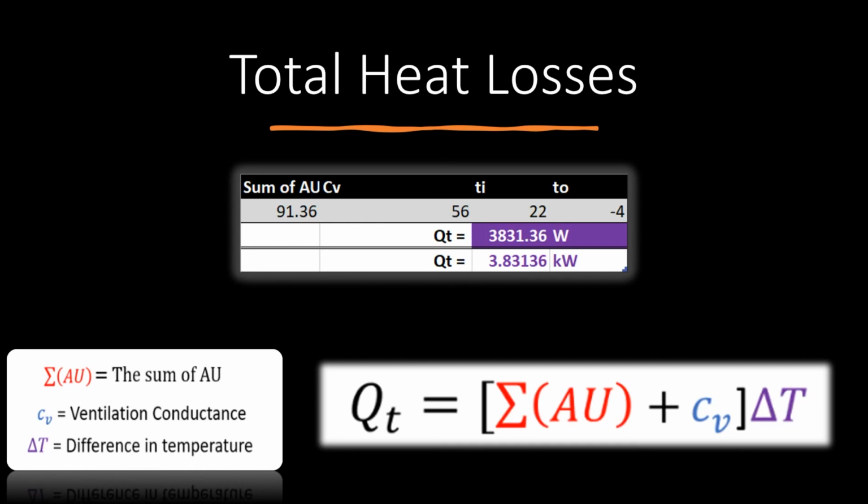So that's that question complete. You might get more complicated variations, but it's always going to be that simple process. The only other thing you might have in terms of extra difficulty would be, say, if the room above or the room below was divided up into more than one room, so you then had to divide your floor or ceiling fabric for your room up into multiple parts. But this is pretty much you finished the standard heat loss question.